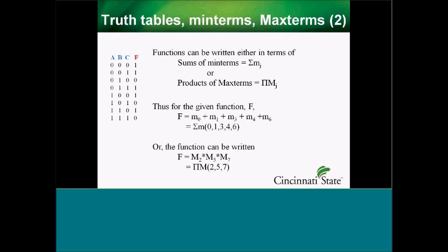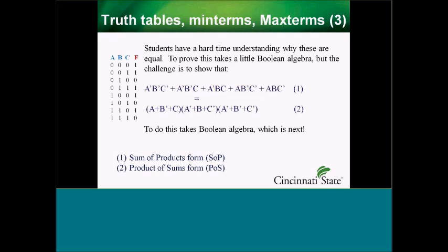We're actually not going to talk a lot about doing K-maps with maxterms, but I have a tutorial which covers it. The students do have a difficult time understanding exactly why these are equal. They look very different. Even when you go into De Morgan's equivalent, which we'll talk about a little bit, they're not really equivalent in this regard. What you're really doing is aiming for the zeros on one and the ones on the other. They're inverse functions.